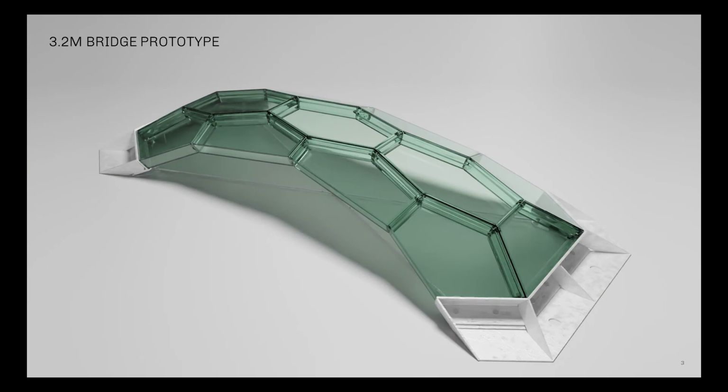This paper presents a smaller bridge prototype to address the challenges of the larger bridge regarding form finding, detail developments, fabrication constraints, and assembly logic. The compression-only prototype is designed for prefabrication as a modular system using PolyFrame for Rhino. There are 13 hollow glass units in this prototype, and they can be prefabricated and assembled on site.